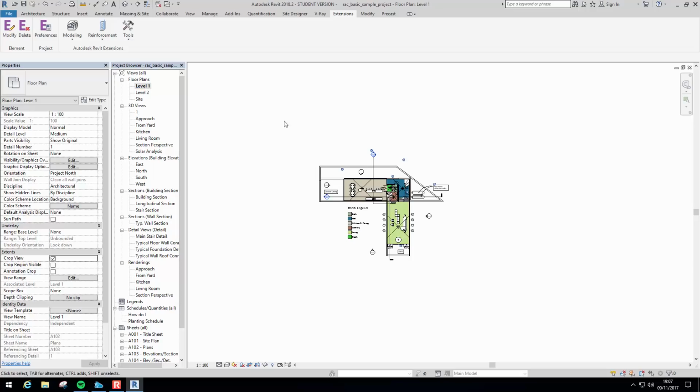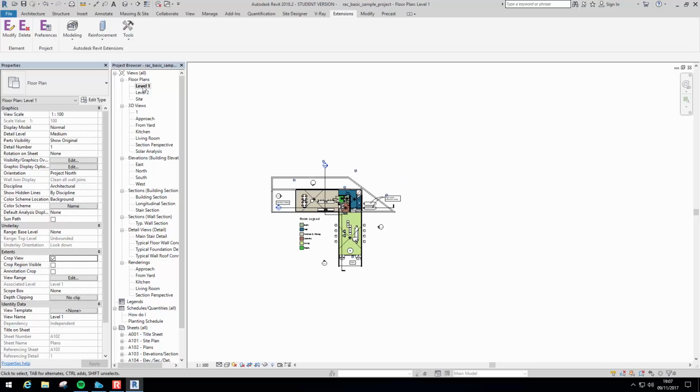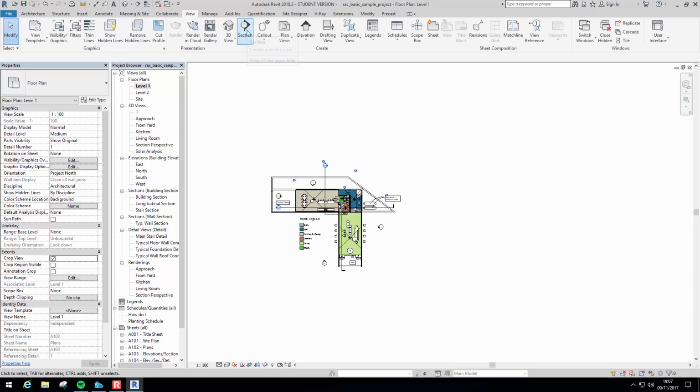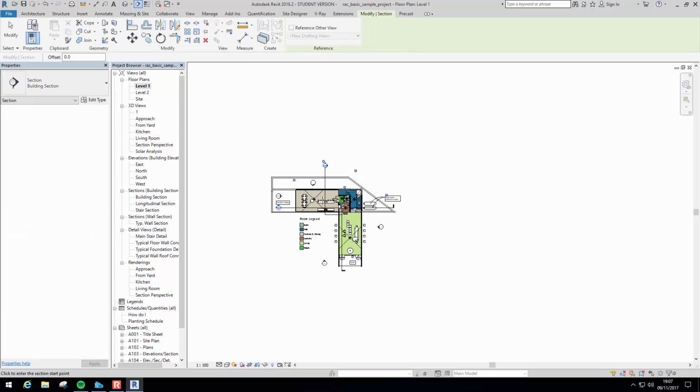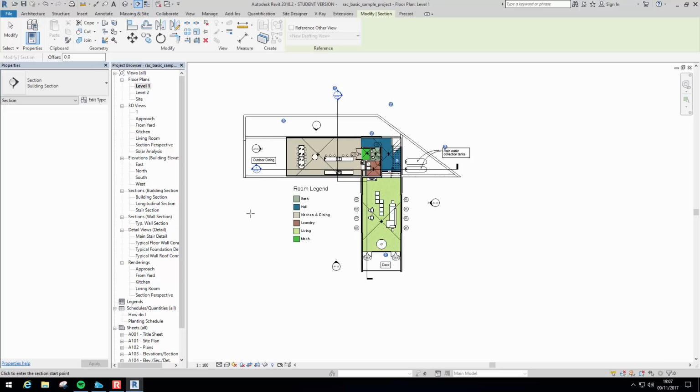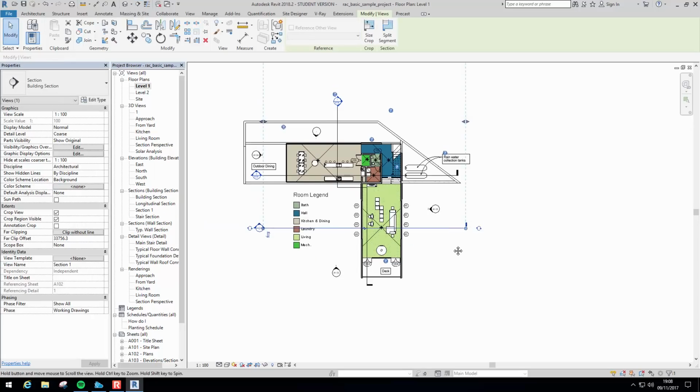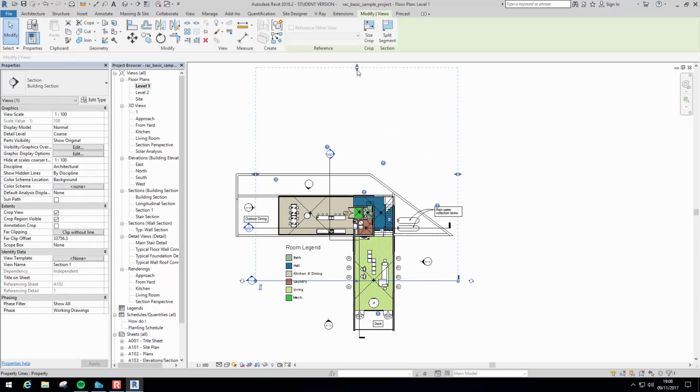Whenever you want to create a section, you need to go to a plan. So you go to plan, you go to view, and there's a little section tool there. So I'm just going to take a section through here. If I left click, drag, right click, that creates a section for you. Now that's the view range. So I'm standing here, cutting through the building, and this dashed line highlights how far I can view the model. So I can extend it or reduce it.